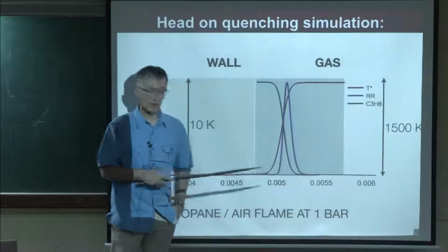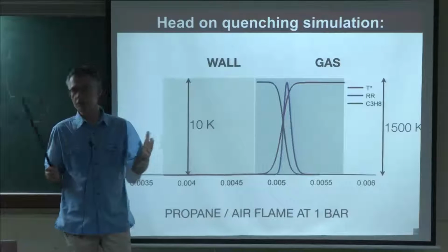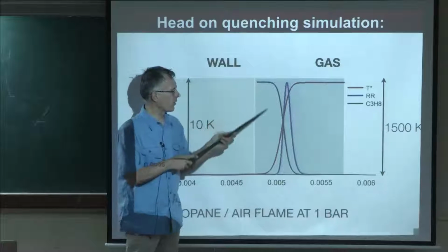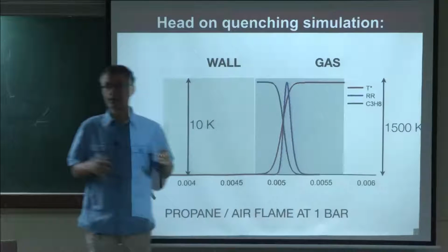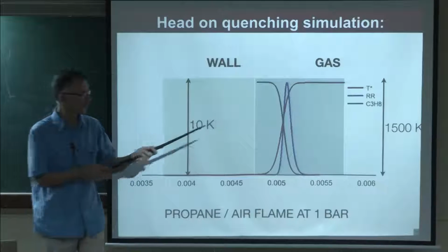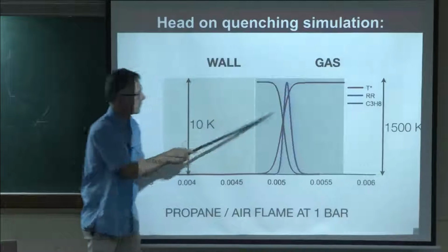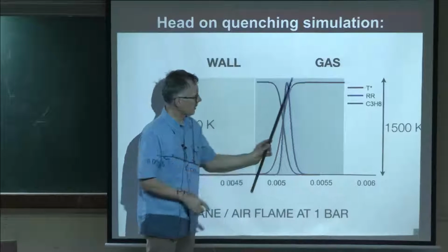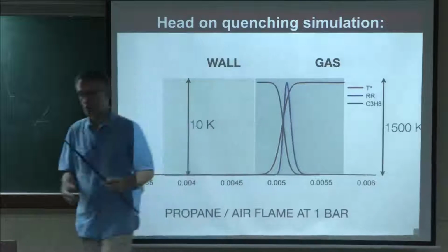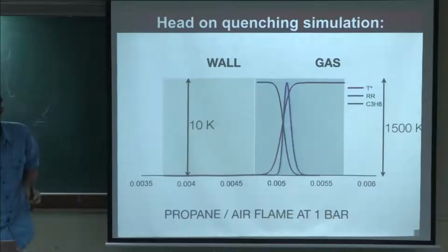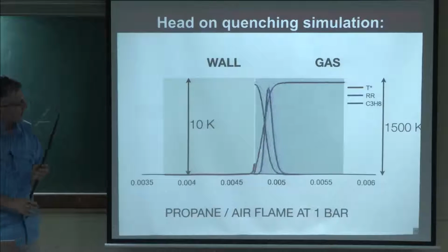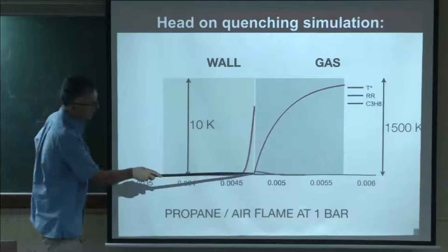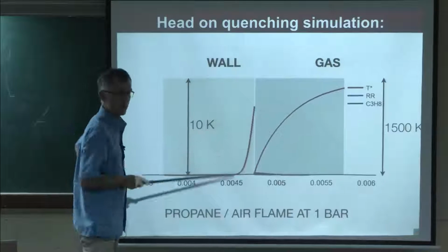And then after that, when everything is quenched, we just have a diffusion problem. The fuel which is left here will slowly diffuse to this side, but it cannot burn anymore. It's just diffusing. And the heat here will slowly diffuse. That means that this point here will actually recede and go in this direction just because it's a heat transfer problem in 1D. So look at this, quenching. The fuel is slowly going down, and the temperature is slowly diffusing.